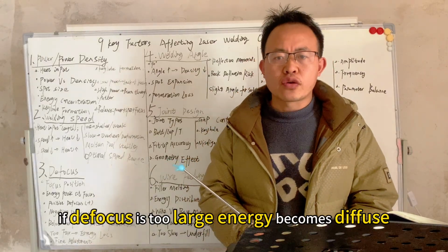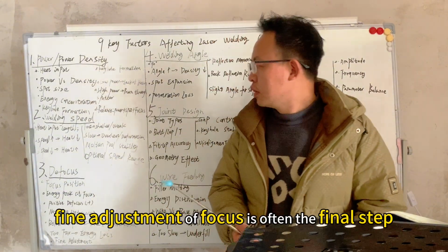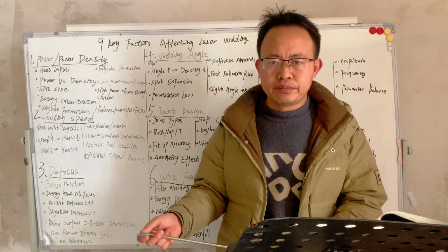If defocus is too large, energy becomes diffuse. The weld becomes shallow and unstable. Fine adjustment of focus is often the final step to optimize weld quality.